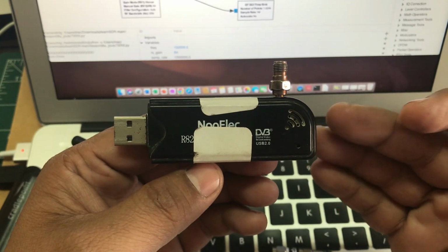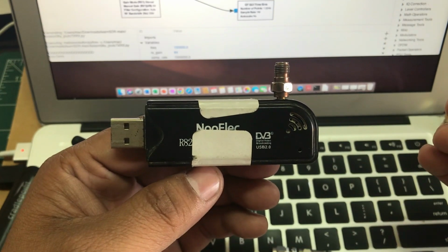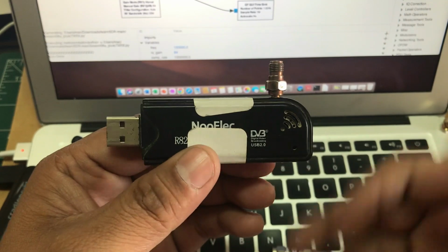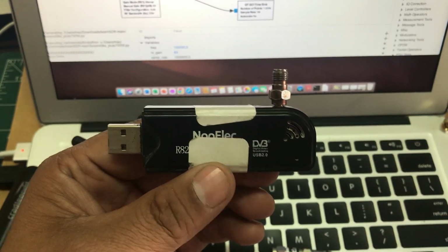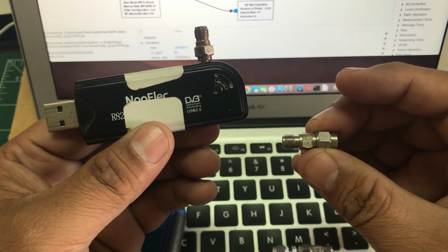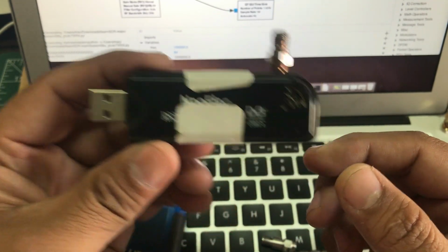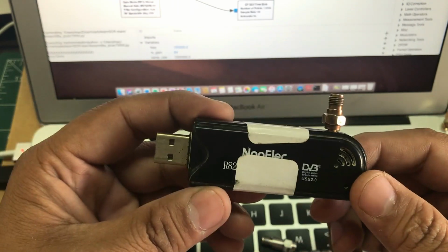I'll first receive the signal and find out what the baseline is without the attenuator. Then I'm going to mount my attenuator again and see how much my signal went down with the help of one of these, so we can see the functionality. So this is the cheapest way of checking to see if your attenuators are properly working.